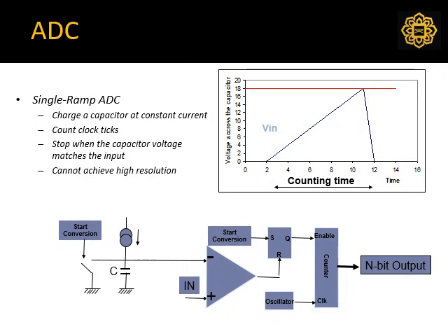And then you have single ramp. In this case, you have the capacitor value. You turn on and off different capacitor values, and accordingly you check the voltage. Again, you do the comparison, and finally you will get the n-bit output values of your analog voltage.